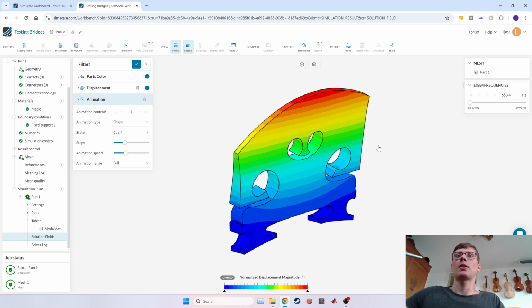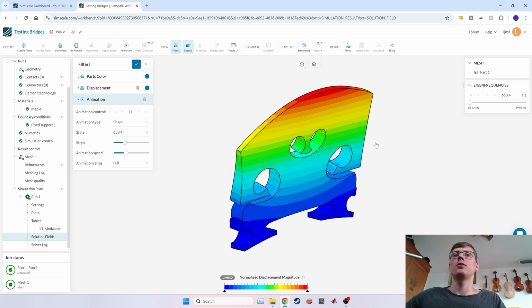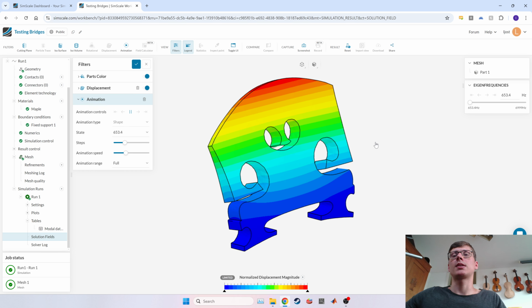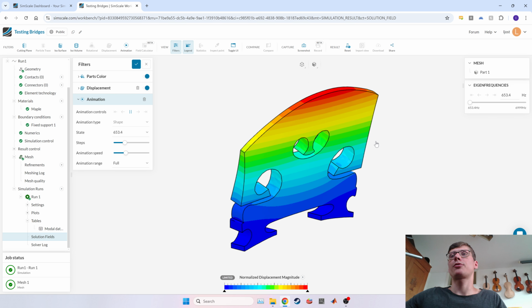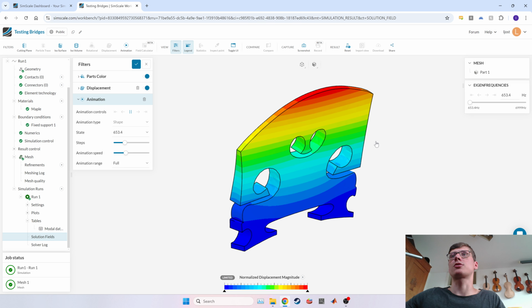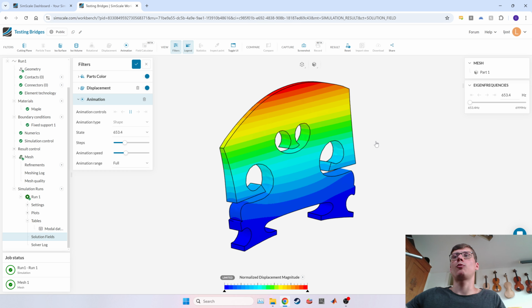And then in the real life tests that we've done so far in Vilfava, we also found that overall, still when considering all these variables, the real life results were always at slightly higher frequencies than the simulated results. So if you find, oh, I'm actually predicting 3000 Hertz and measuring 3200, don't be too worried. We measured the same. We're looking into why that is the case. We still don't know as of yet.